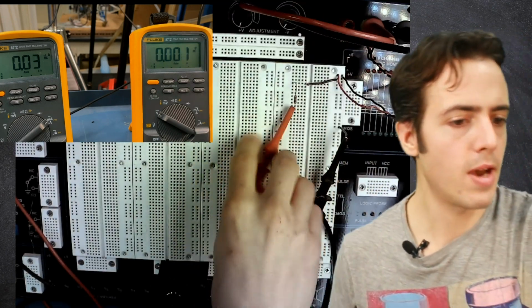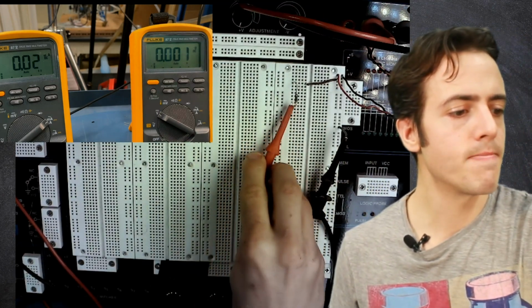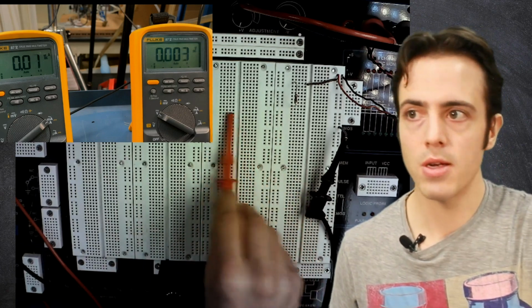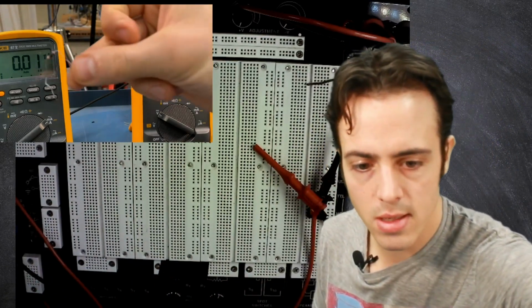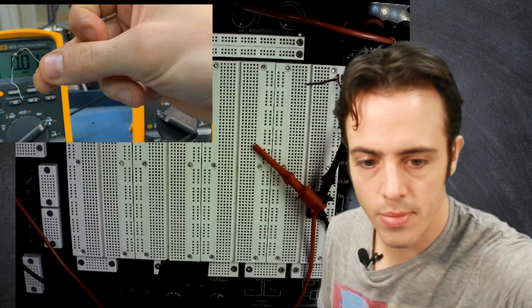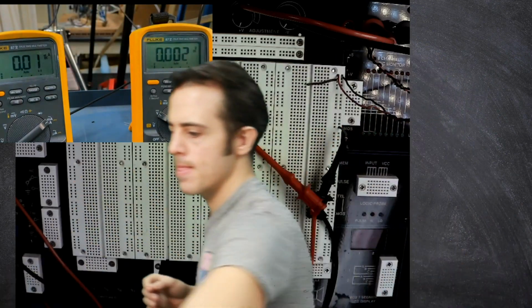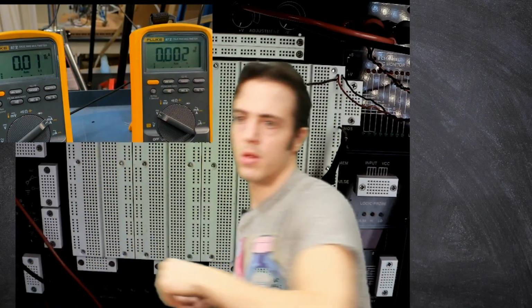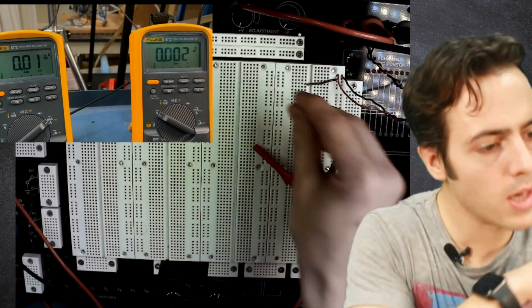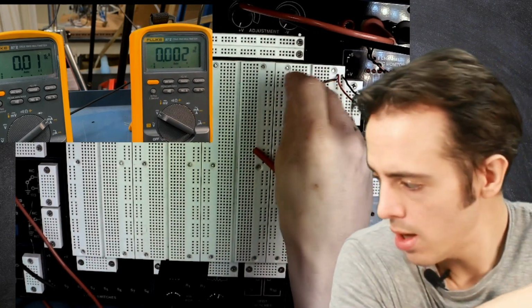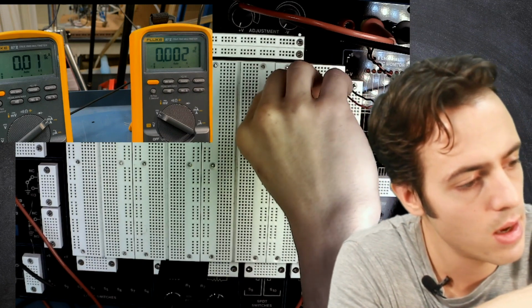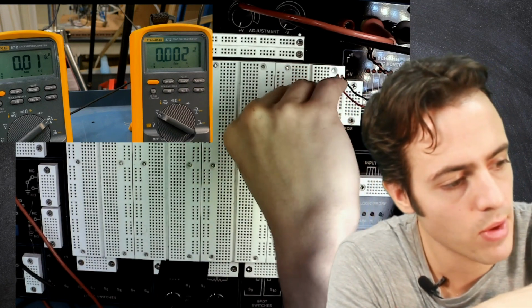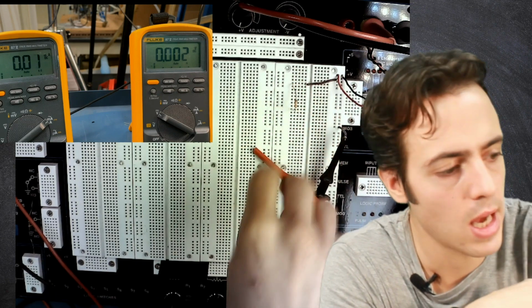So let's turn this right down. Breadboard's off anyway, and all I now need to do is take out this jump resistor. This one's going to be thrown away because it's all burned up. Let's see if we can see that. It's all burned up. So we can get rid of that now. Okay, so I'm going to connect this, resistor 1, here. Doesn't matter where I put it in because the circuit's being completed through the ammeter.